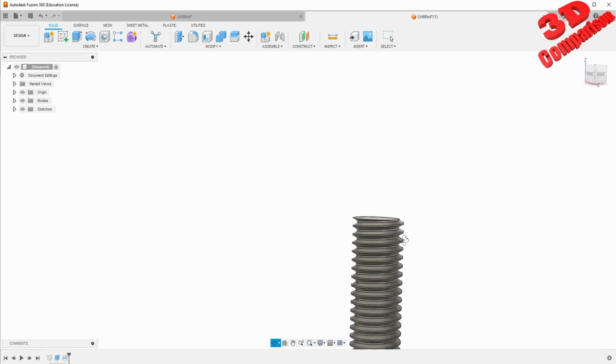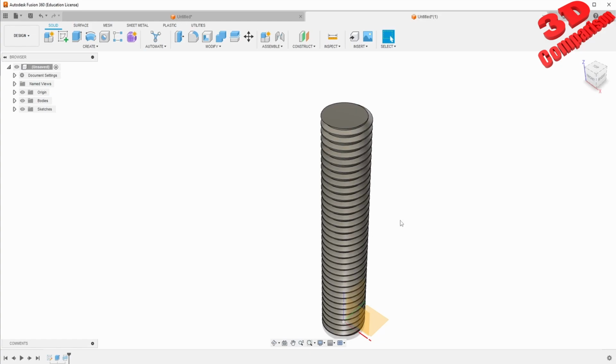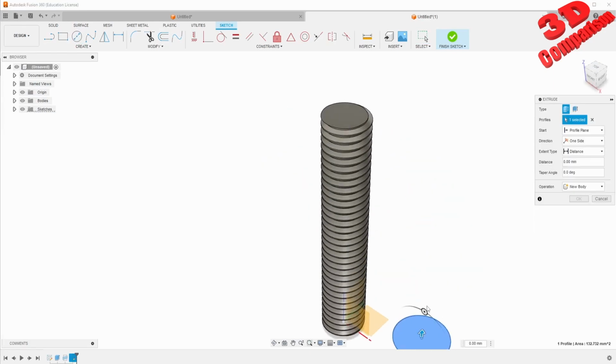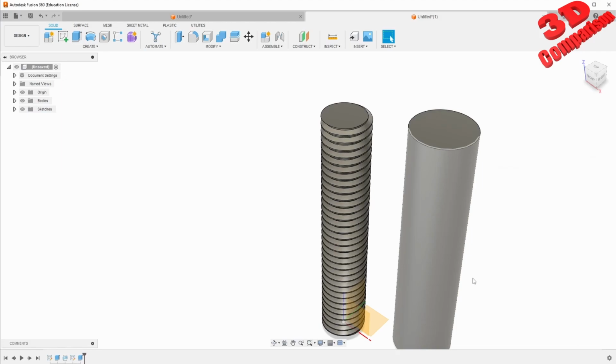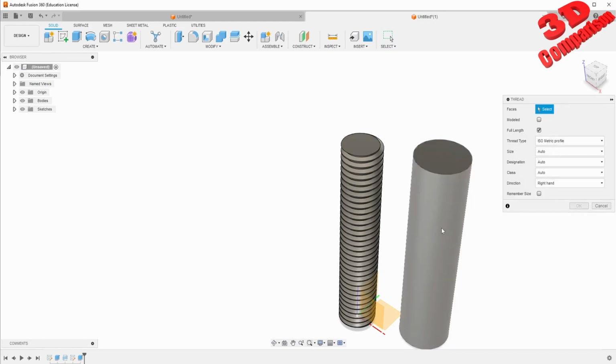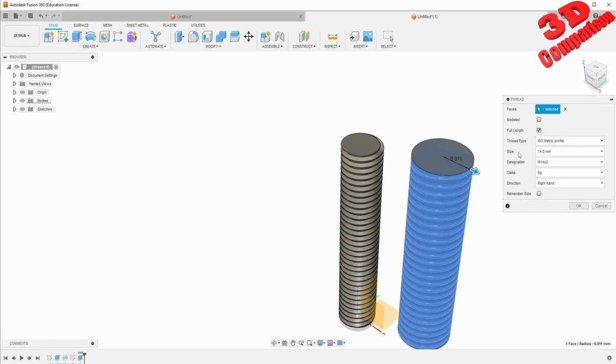We saw that this takes, let's say, only a few seconds. And let me also show you, for example, if I create this to be 13 millimeters, afterwards have it extruded 50 millimeters. Again, if I go for threads, so S for shortcut, type in thread. This will automatically see that the closer value will be 14 in this case.